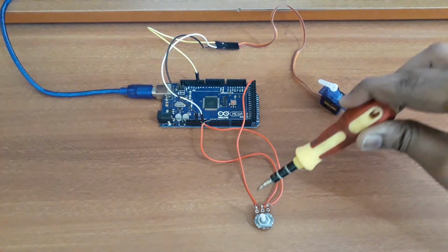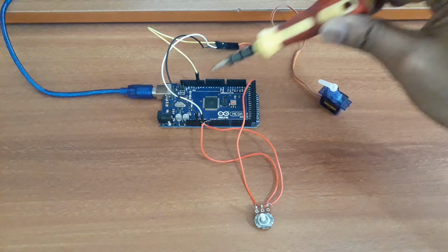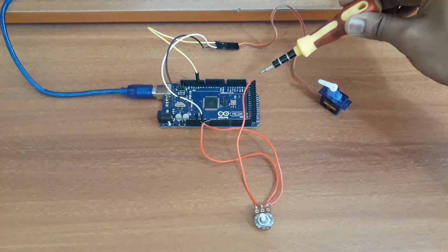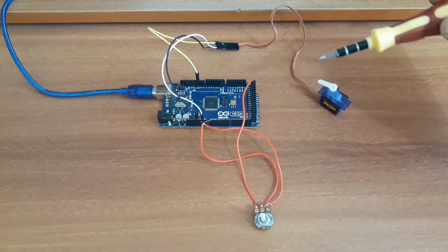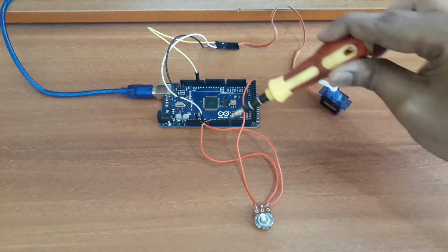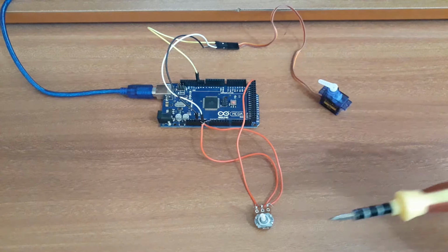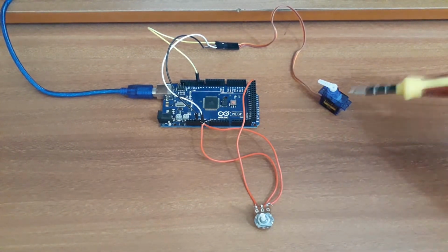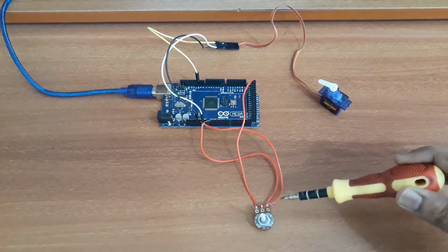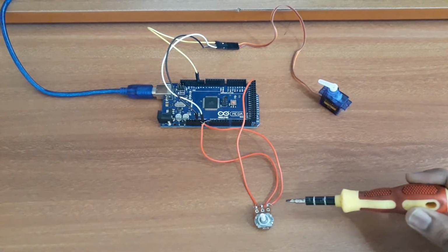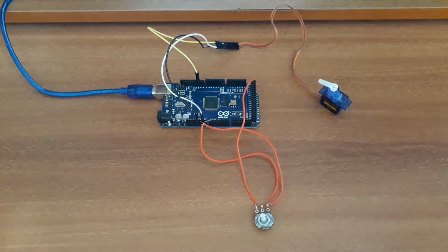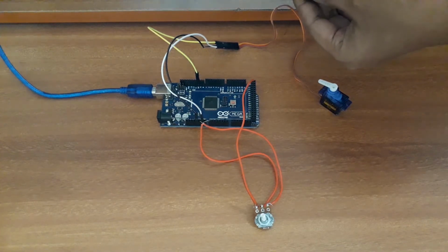And for the potentiometer, the first pin goes to the 5 volt positive supply. As I am using the Mega, there are a total of 3 different 5 volt supply pins. These are the two. Then the center pin I connected with the analog A0, as I am sending the analog signal with the help of the potentiometer, and with the help of the potentiometer I am controlling the servo motor position. Because of that, the center pin I connected with A0, and the last pin I connected with the ground. This is the whole circuit diagram. Already I uploaded the code. Now I will connect the supply.